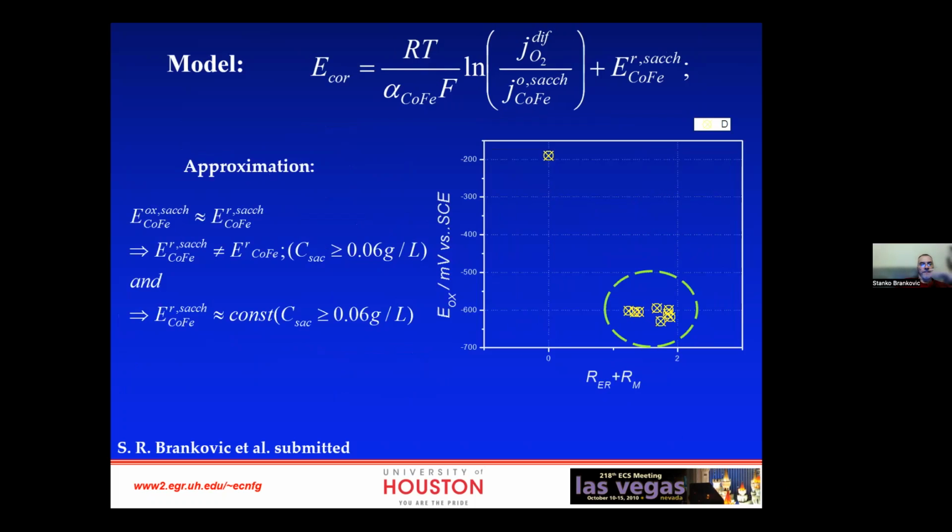So now, interestingly enough, if we look at the onset of the dissolution of these alloys during the anodic polarization, what we see is that the alloys that do not have any presence of the additives in the solution, which we electrodeposit as pure alloys, completely differ when it comes to this onset of the anodic dissolution, whereas all alloys with additives, pretty much regardless how much saccharin you have in solution, have a common anodic onset dissolution potential, and the alloys electrodeposited without saccharin in the solution actually completely look different, basically.